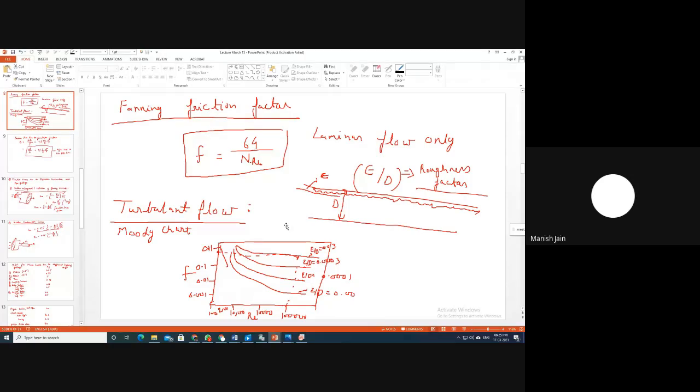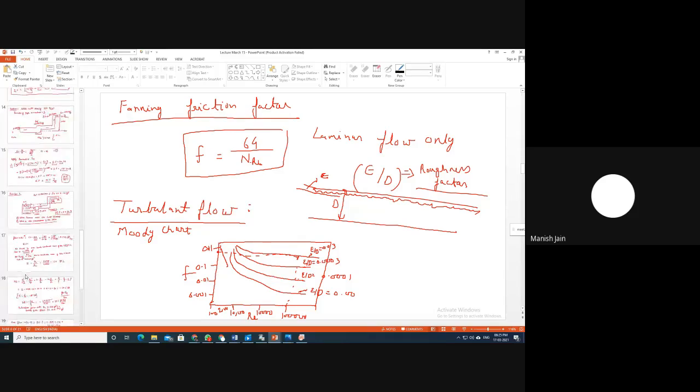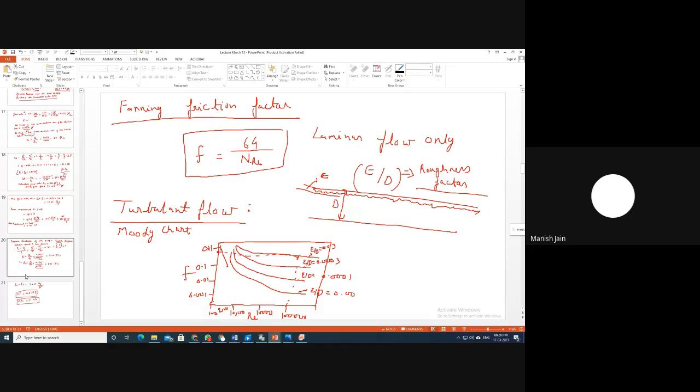And always remember, where energy balance is happening, the energy balance is per unit mass. Okay, the Bernoulli equation that is defined is per unit mass, energy per unit mass. But where you have to state the power output for the system, that should be given in the energy per unit time. Okay, power of the pump, power of the system, electric power requirement, that should be given in the energy per unit time. So multiply with the mass flow rate, it will convert it into the energy per unit time. Otherwise, the Bernoulli equation is given in the energy per unit mass, joules per kg, or lbf divided by lbm. Okay, so this is the unit of the Bernoulli equation. And when you use the power, convert it into the energy per second.